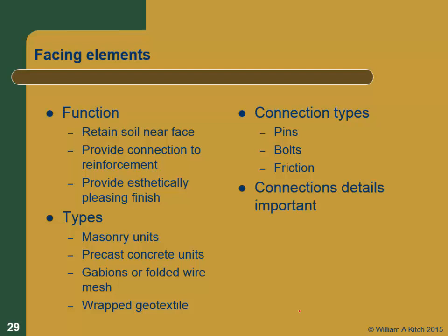The connection details are important. There have been a lot of wall failures due to poor connection details. So if you have proprietary connections, in fact, all the facing manufacturers will give you specifications for the connections. You need to follow them.